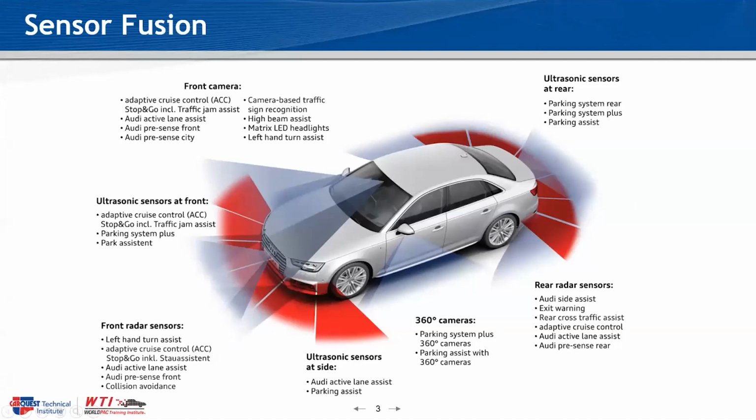What I find the most important about every situation in advanced driver assist systems is the sensor fusion that's involved, due to the overall resolution that it provides by having multiple systems overlap and cross-check certain things. That's the biggest part, but I do want to pose a question just in the very beginning. If you guys want to post in the chat, preferably, I think that would be better: do these things set misalignment DTCs? Can we have a misalignment DTC on a camera or a radar system or any of the other ones? And if so, how do you propose that that's set? Anyone on the panel care to give a shot at answering that?